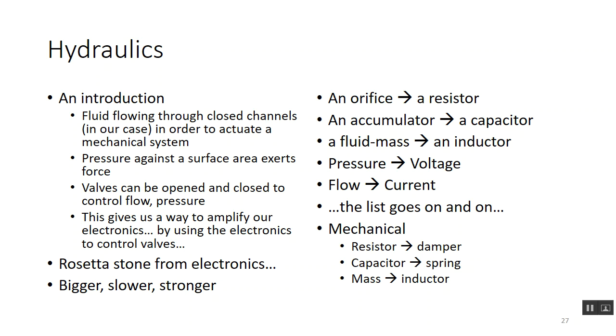And it's so cool because it boils down to exactly the same thing as electronics. When I started getting into this, I was blessed to have some people around me that knew more about it, so I could ask them stuff, and in my head I was building this little Rosetta Stone of, okay, when I think about an amplifier, that's this thing in hydraulics, and when I think about a resistor in an electrical circuit, because I do that stuff in my sleep, that's an orifice, which is just a restriction of flow.